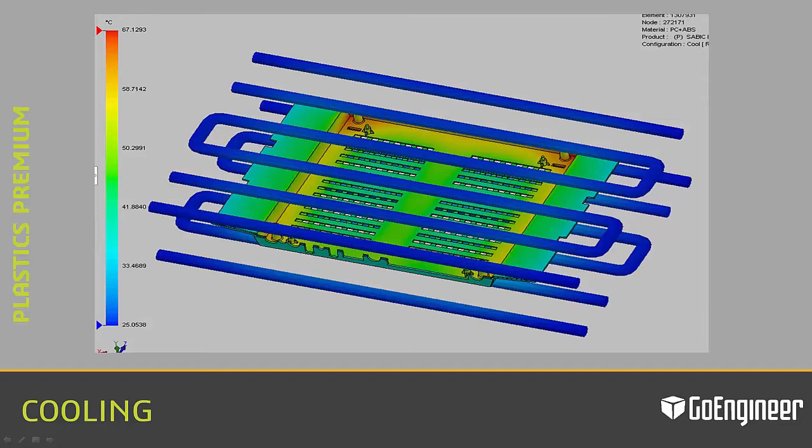The cooling analysis will simulate the thermodynamic effects of cooling channels, baffles, bubblers, and the mold. Cooling occurs throughout all stages of the injection molding process from the fill stage through ejection. The rate of cooling has a significant effect on part dimensions and influences part defects. If uniform cooling is maintained, the residual stress within the part can be reduced, thereby minimizing the risk of warpage and cracking.